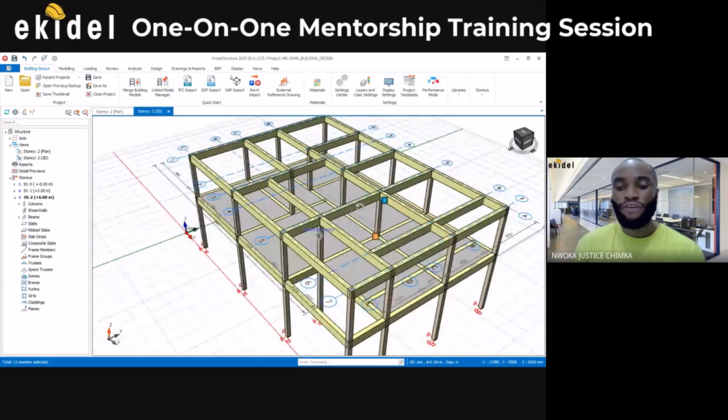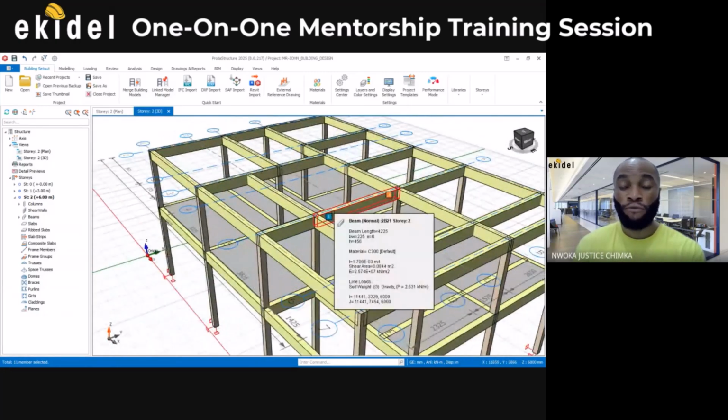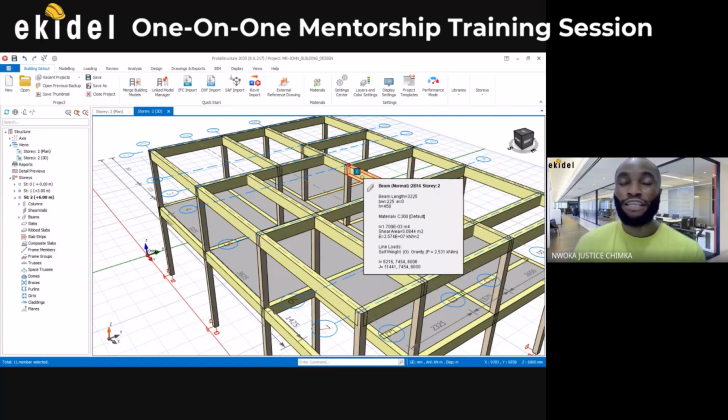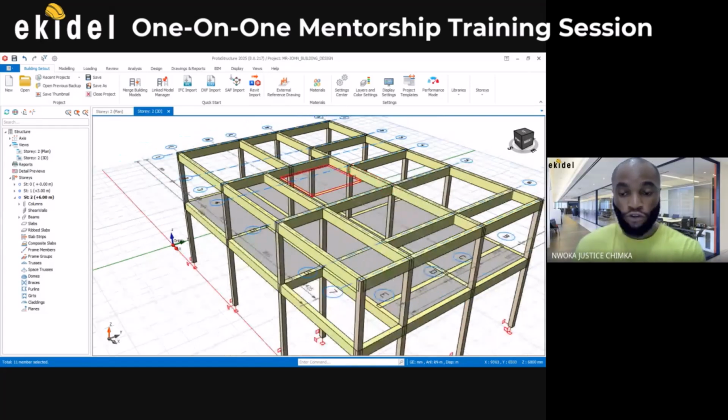Now that we have removed the slab from the roof, from the second floor, which is the roof beam now, we need to reduce the depth of the beam, because what makes the beam depth is the slab load plus the beam. So right now that we have removed the slab of 150, we need to subtract it from the beam depth, which will now make the beam depth for the roof to be what? 300. Yes. You understand?